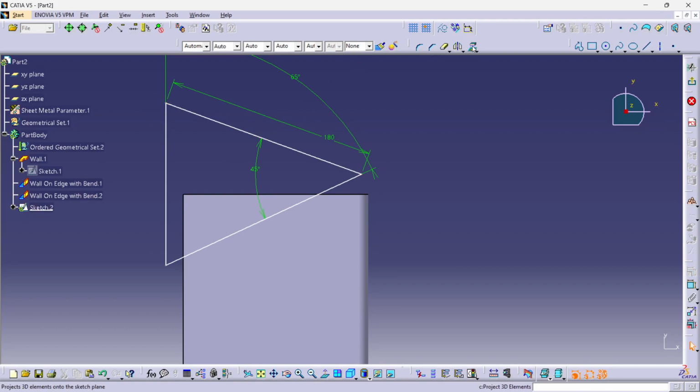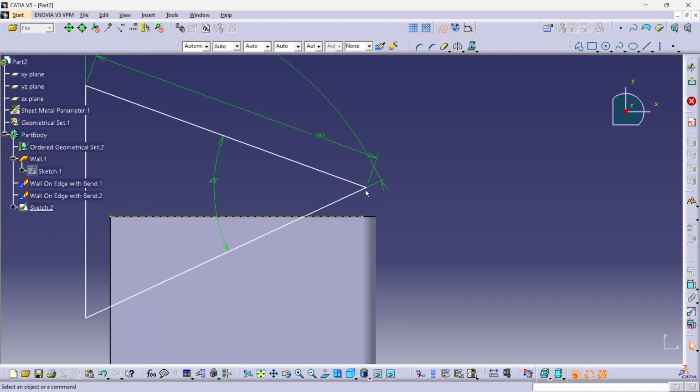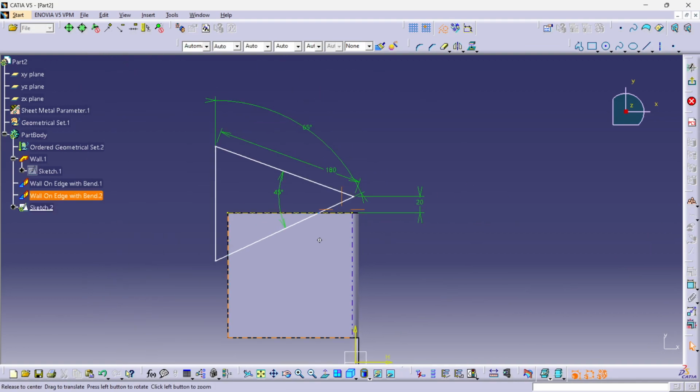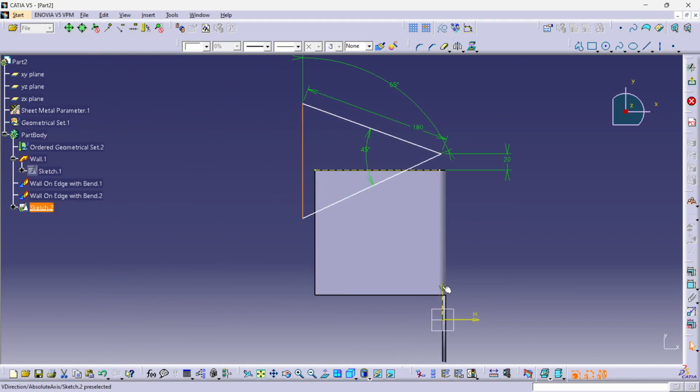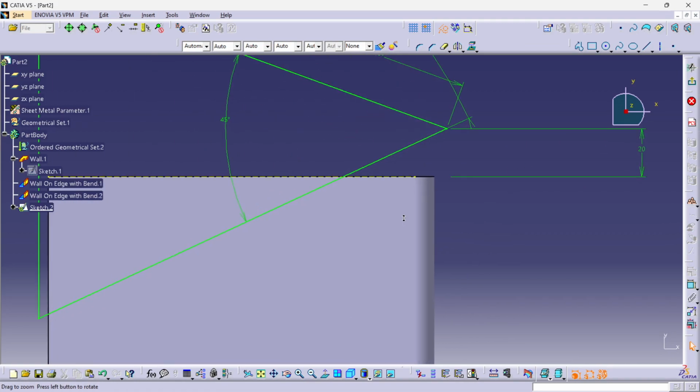And use the term called 3D projection, right? So what I need to do, just click on this. Now it is a line. Now just click on that, convert it to the construction line. Okay, now it's a construction line. Now just select the point here, this one, go for dimension as 20. Good. And the distance between these two should be 160. Now we are constrained and all is good.